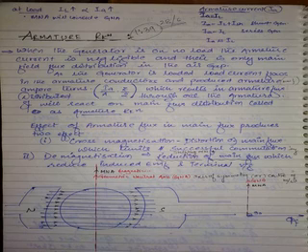Can we say that? In this particular figure, I am showing only main flux flowing from north to south, always like that. If there is only main flux, it means the machine is on no load. Assume like that. If there is only main flux, MNA and GNA coincide with each other, as the MNA is at 90 degrees to the flux lines. So MNA is always making 90 degrees with the flux lines.